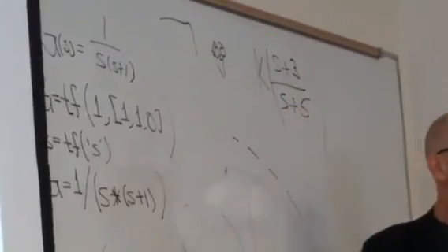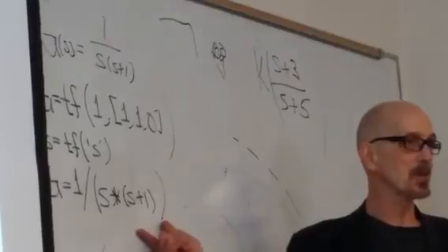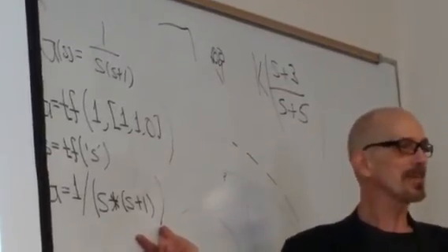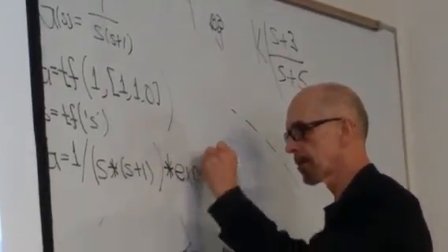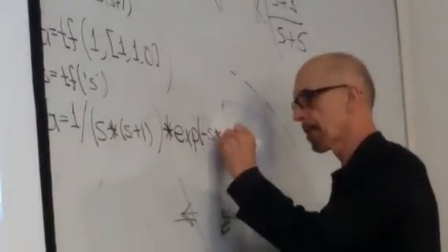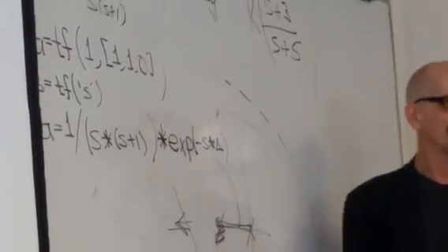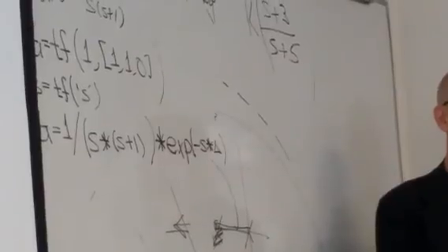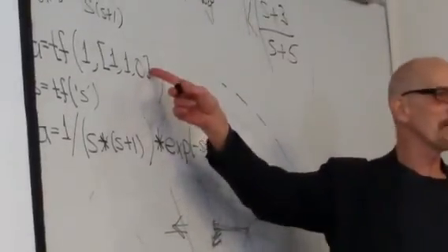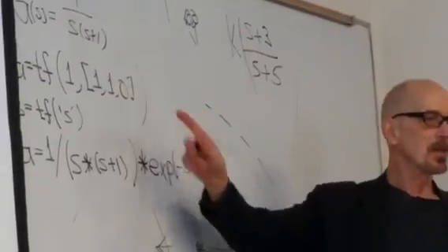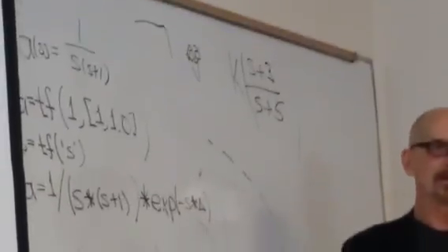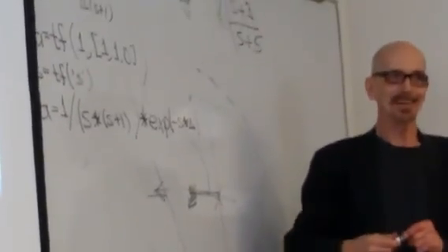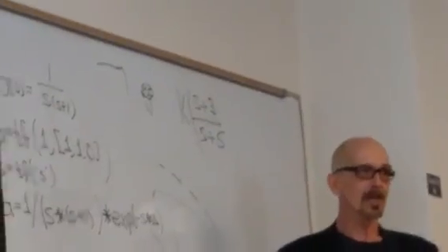That way, this way for time delays is expedient, to get a time delay in here, whereas this way you don't have polynomials anymore, so you can't do it. So this is how you would incorporate a delta second time delay. Now remember, that's for a delta second time delay in the forward loop, but you're looking at the open loop. So be careful with that.